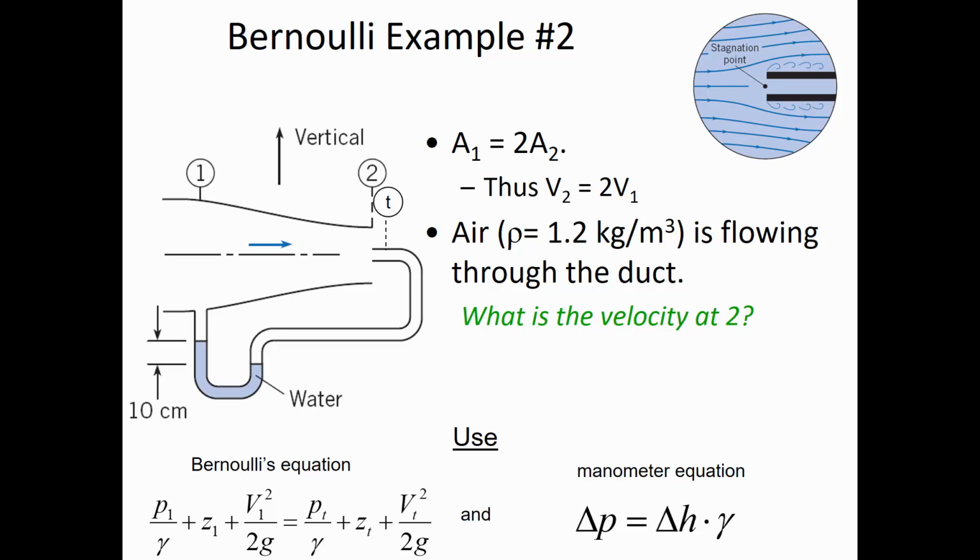But then, as we move down through a fluid as dense as water, the pressure changes more rapidly because water has a high density. And so we're saying the pressure at 1 plus delta H times gamma, so some pressure change, and then that gets us to this location, the pressure here. Then throughout this tube, the pressure is basically constant.